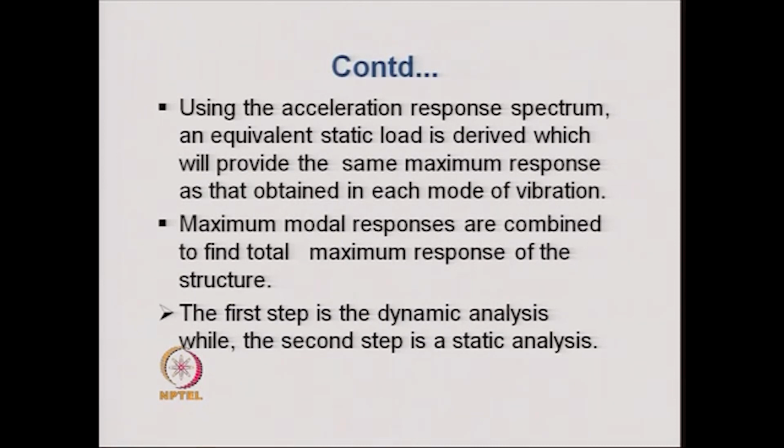The first step, that is finding the mode shapes and frequency of the structure, is a dynamic analysis, while the second step is a static analysis, because we obtain an equivalent static load and carry out a static analysis.